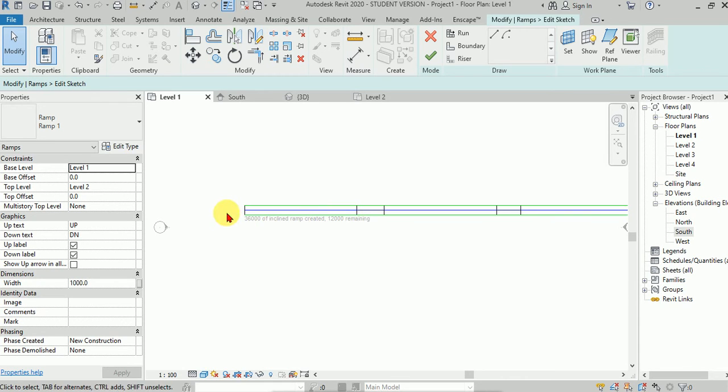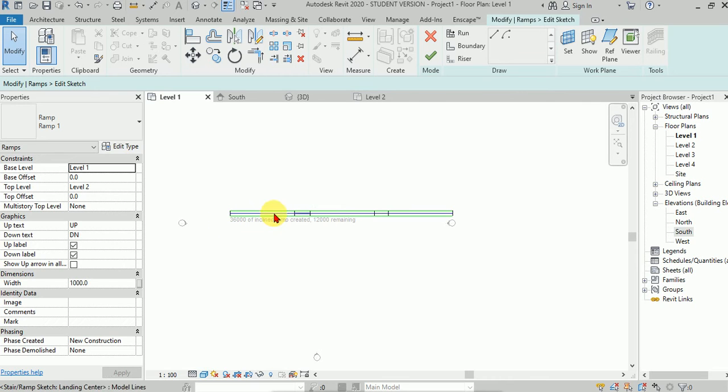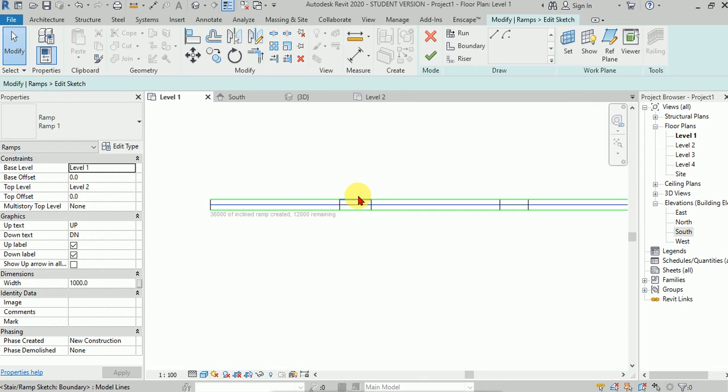That is why usually we have mid landings after 10 to 11 steps. Similarly, ramps are made for whom? They are for the specially challenged, like wheelchair users. In that case, can a wheelchair user travel a ramp which doesn't have a mid landing, for like 50 meters in a row? No, you cannot. By any slope you cannot travel. So that is why after 12 meters you have a mid landing. It can vary: after 10 meters, after 12 meters, you can give a mid landing. You need to specify a mid landing.